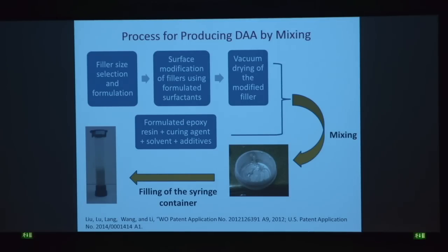We sized the filler, we picked the filler size, that is the silver nanoparticle size, surface modification, vacuum drying, we formulated the epoxy and mixed them. But think about it. You have to mix it in such a way that they would distribute uniformly. That turned out not to be easy.